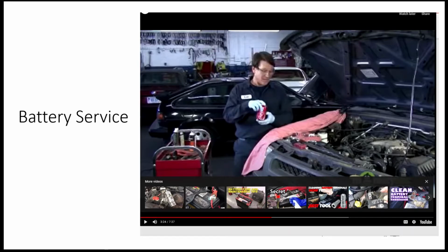Good stuff. So that's a good use for that if you don't have the baking soda and water, or the battery terminal cleaner that he sprayed on. I do like the method of him putting a rag underneath to capture all the stuff. The main thing is that the rag needs to be washed out and put into the soiled rag bin, where it's not going to be grabbed by anybody else.